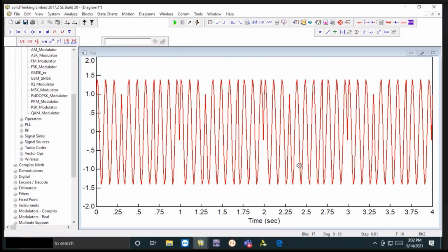So here you have to understand that first we'll apply the demultiplexer to separate them on the basis of the odd and even position. And then finally, we are not going to apply the multiplexer. The multiplexer will be applied at the receiver end. Here we have just added them normally at the position of appearance. Okay. So it is a normal algebraic addition of the two signals, the odd and the even PSK. This will transmit at the receiver end.